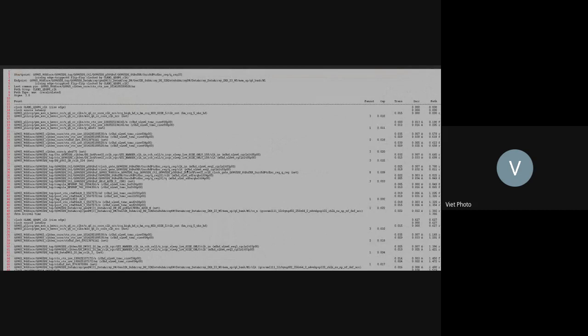Okay, this one is the clock gate that I talked to you about, right? So you go through the clock gate, and after the clock gate you go to the flop. This one, SDF, the DF here is the flop. So I go to the clock pin here. The arrival time here is 415, right? So they calculate like that, from 0. The timing is not calculated only from the clock pin, but from the source of the clock, which is 0 picosecond here, until the clock pin here is 415. Then I go through the clock to Q, and you have 34 picosecond.